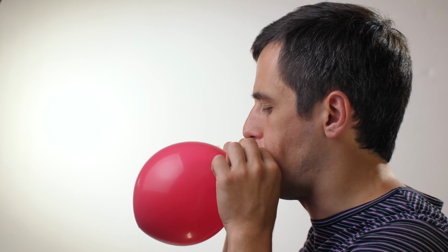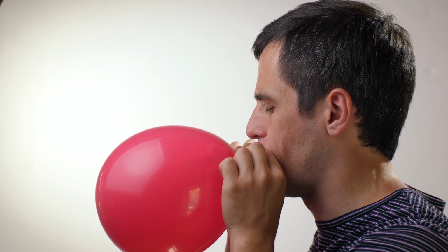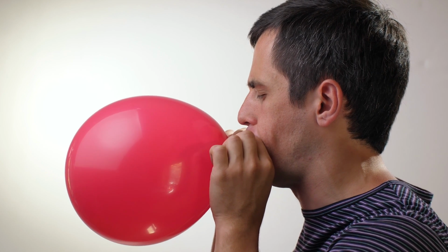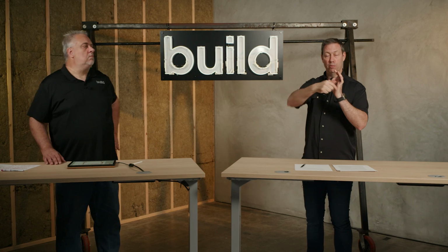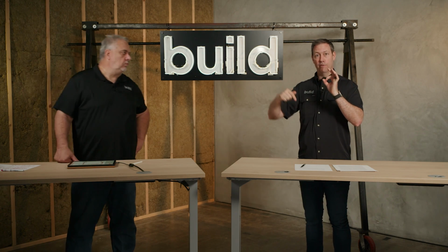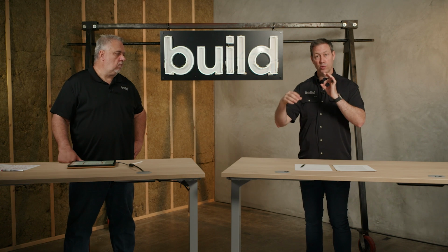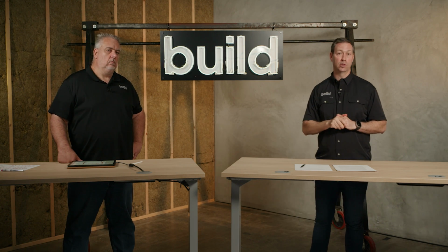If you could go back to that blower door example, I like to liken it to a balloon. It's pressurizing that balloon, and the blower fan is calibrated so that if we know the pressure difference between inside and out, we're able to figure out how many pinholes, pin pricks, or big holes we have in this building envelope. The more the pin pricks, the more the holes, the higher the blower door score. That's where that 5 ACH 50 comes from.